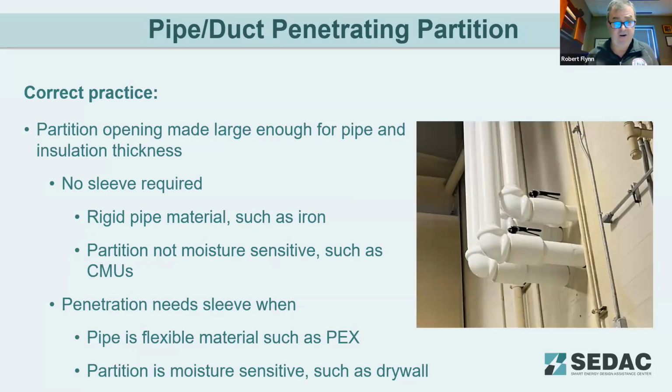There was a statement here from one of our participants. I found specifying CalSil, which is a different type of insulation, as an insert on pipe hangers allows these devices to be installed by mechanical contractors rather than an insulator. Then it's easier for an insulator to insulate between hangers than to do jackets all over.